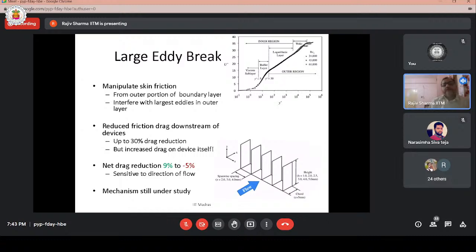It's a fairly well-known concept in the field of vehicle design that any appendages to the body will adversely affect the drag. So if you have a bare hull drag and you add on different appendages, with all appendages, your actual drag may be 100%, 150%, 200% higher than the bare hull drag. That means the appendages will add to the drag approximately 100% to 200%. That is actually happening here also.